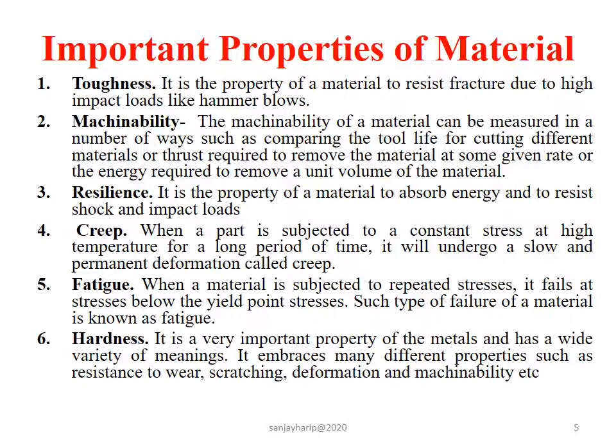Fatigue. When material is subjected to repeated stresses, it fails at stress below yield stress. Such failure is known as fatigue. Fatigue can form crack. This property is to be considered in designing of shafts, connecting rod, springs.